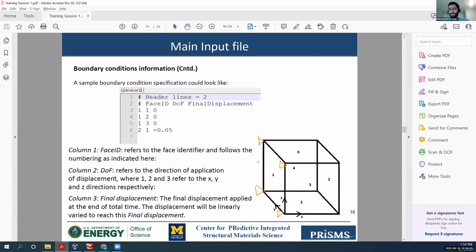It's like modeling a symmetric boundary condition. Imagine in 2D, and the loading is symmetric, you can model 1/4 of it and put a roller here. Now, if it's 3D, this is what we are trying to model.